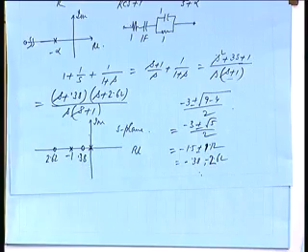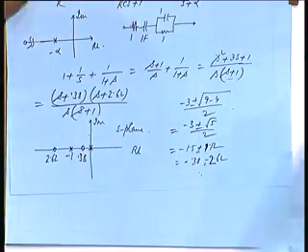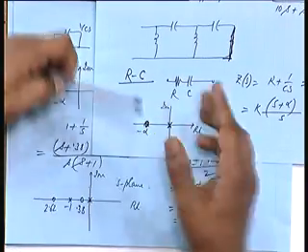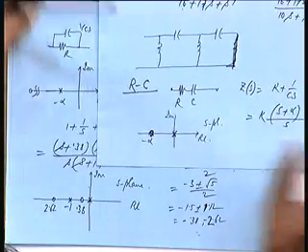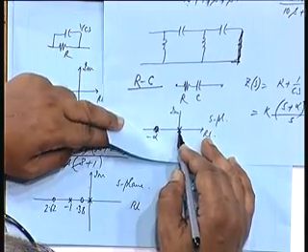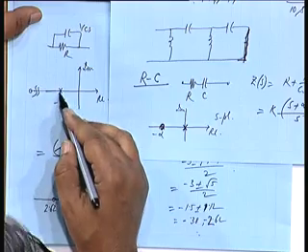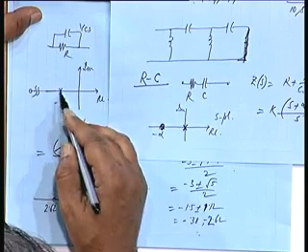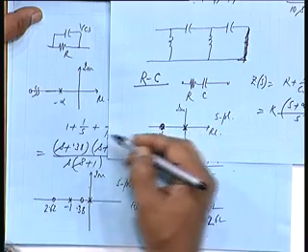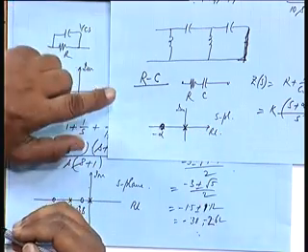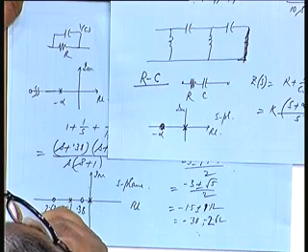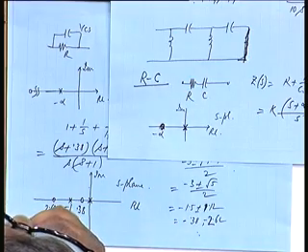Okay. So, if you have observed the pole 0 configuration for these three, you can take a few more examples and then see for yourself. Either it may be starting from the origin or it may not start from the origin, but the first one is a pole, it starts with a pole. As you go along the negative real axis, first of all poles and zeros are all on the negative real axis, RC circuit, there is no scope for oscillation.